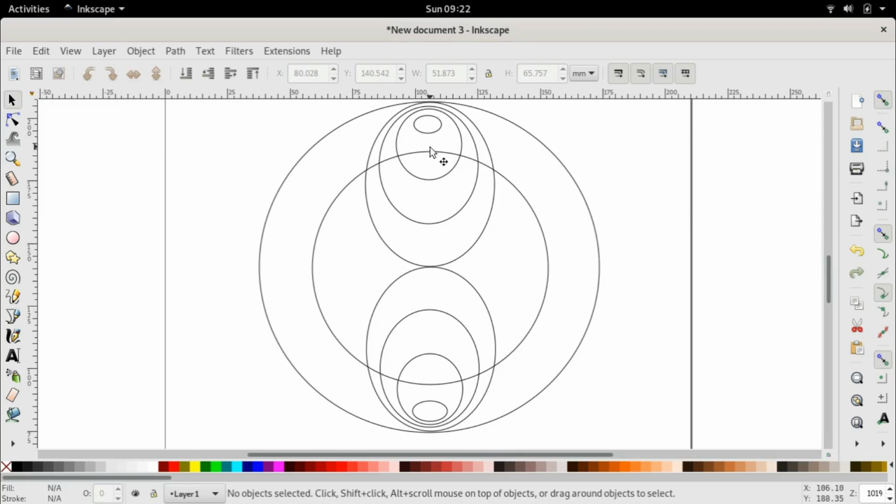So, by applying right hand thumb rule, if we say that the current is flowing into the page in this slot, then these flux lines will be in the clockwise direction. And if the current is flowing out of the page in this slot, then by using right hand thumb rule, the flux lines will be in the counterclockwise direction.